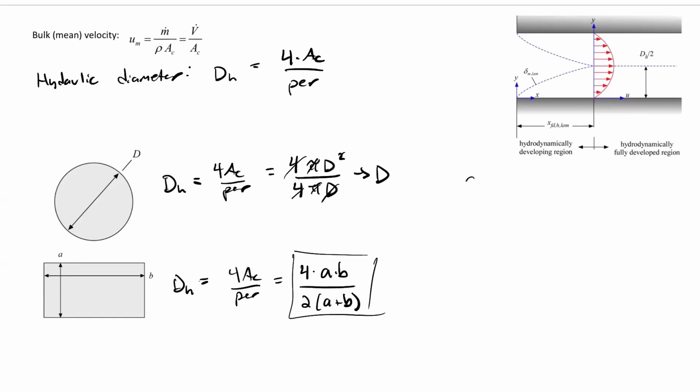If we do that, we have delta_M laminar. If you remember, delta_M laminar is going to be approximately equal to 2 times the square root of nu times time. This is from our 1D conduction model. We can write that in terms of the flow velocity, so that becomes 2 times the square root of nu times x over the mean velocity. So that gives us the growth of the boundary layer, the thickness of the laminar boundary layer at any position x.